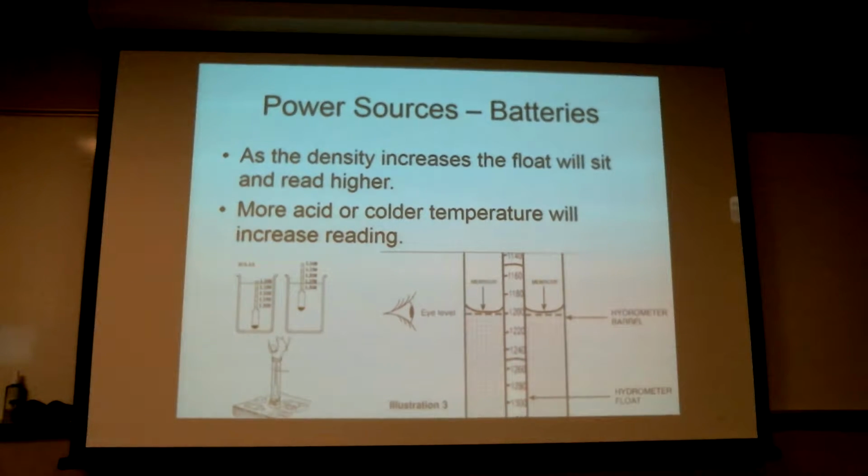Gasoline's even worse. Alcohol is actually better than water. It tends to lay a little flatter. It's not directly correlated to viscosity, but it's a function of capillary action. And if I make a small enough tube, it'll draw the fluid all the way up and fill the tube, capillary action working against gravity.